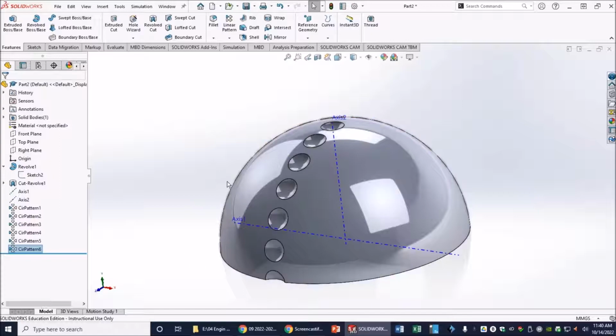When we go ahead and make this an actual sphere later on, the mirror image will complete the dimple. We also are going to 3D print this, so when we put the 2 hemispheres together, it'll still match. So that is how we use circular patterns to get our first row of dimples created on the golf ball. The next one will be creating our circular patterns.